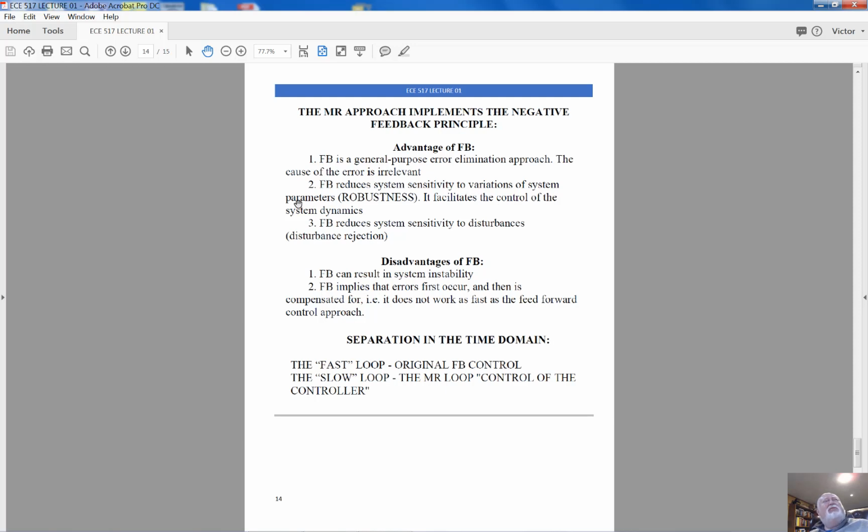If you would check the effect of temperature, for example, on a thermal process, the effect of the outdoor temperature would be quite noticeable. As soon as we introduce negative feedback, we will have quite low and maybe even zero steady state error, which effectively means that feedback would surely reduce sensitivity of the system to external effects. And of course, feedback would reduce system sensitivity to system properties.